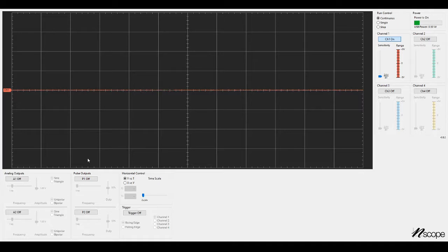Okay, right now I'm just looking at what's coming out of the A1, and it's off, so I don't see anything. I'll turn on channel 2 so we can see the voltage coming from the phototransistor circuit. And if I block it, so now I'm covering it with my hand, it goes down a little, and the light just in my room makes that green line. So this is just not very bright, so the phototransistor voltage is not maxing out.